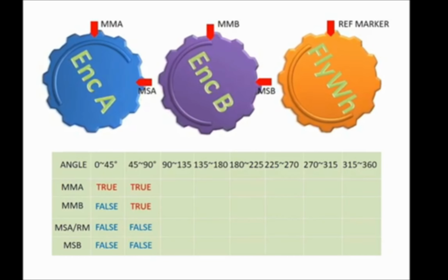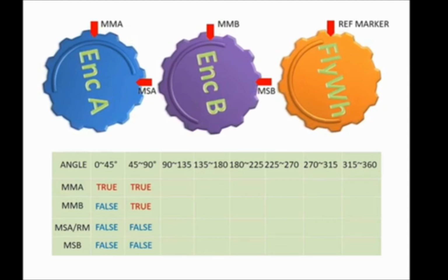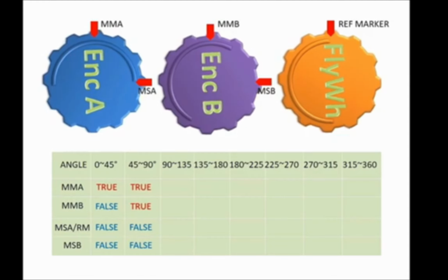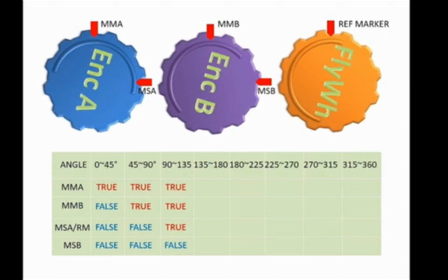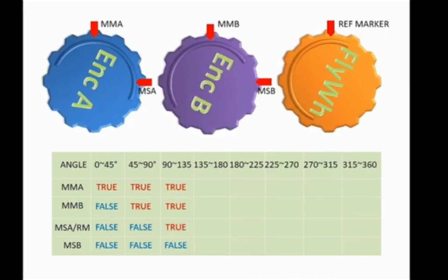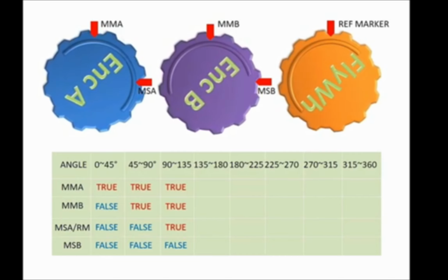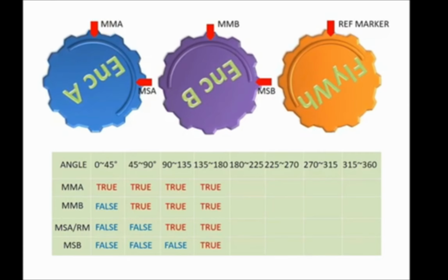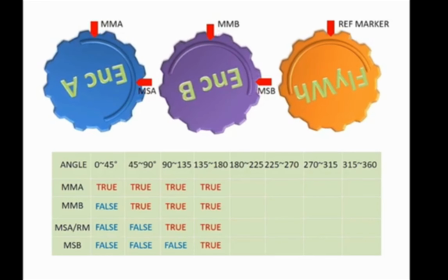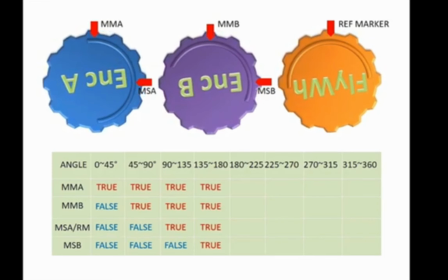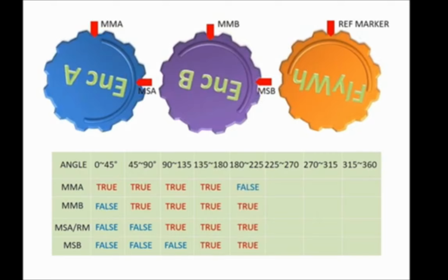This animation will show you, in each position, the status of all 4 sensors in the tabular column. With this we can find which 45 degree position the engine is actually at, so that the unit's starting valve will start for the initial movement. Once one revolution is achieved, the whole system will get reset with that actual position. After that the computer will calculate the correct angle, and all the system will continue to run.